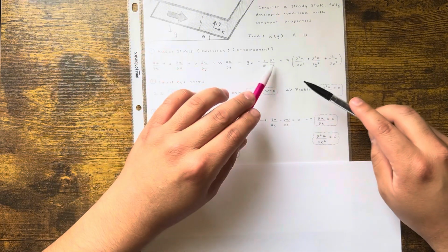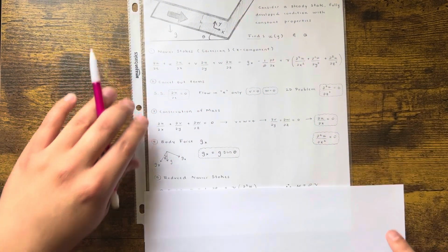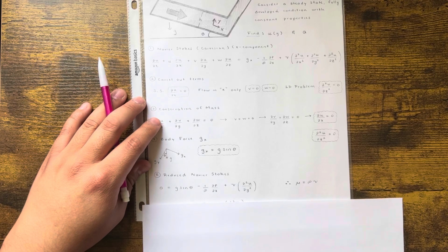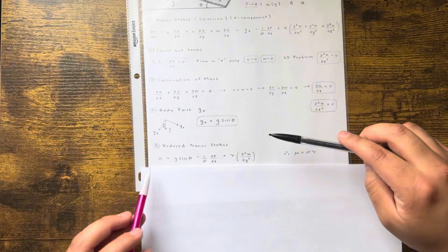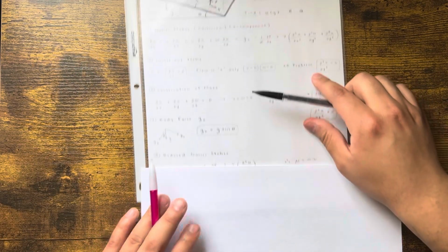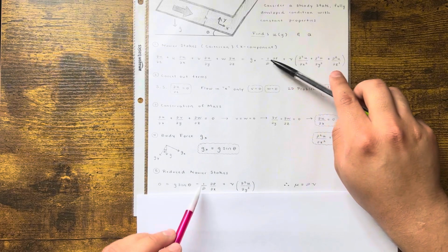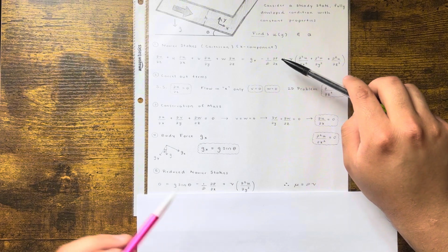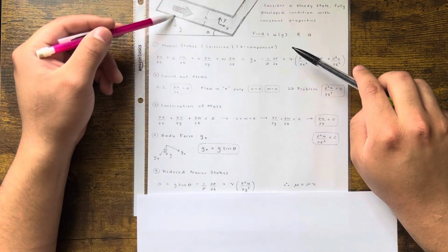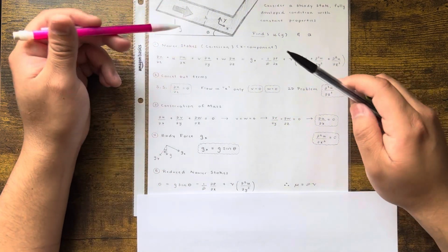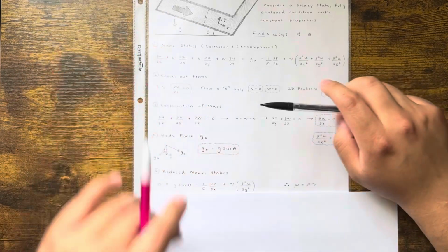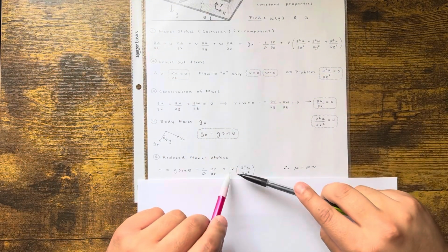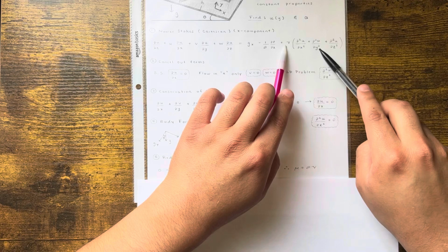There's a pressure that exists that's flowing the fluid, right? So just like that, we have this as our Navier Stokes equation: g sine theta, g of x, minus 1 over density, delta p over delta x. The pressure in the x direction that's moving the flow, because both plates are fixed. So in order for the fluid to move, there has to be a pressure. It has to be something pushing the fluid. And that's what that means, okay? Plus this term. Boom, this times this.